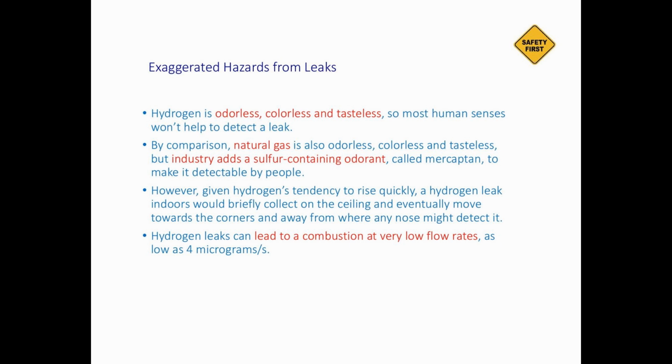By comparison, natural gas is also odorless, colorless, tasteless. As an industry practice, we always add some kind of sulfur-containing odorant, mercaptans. When you have leaks, you can smell it at home. But with hydrogen, we don't add anything, no sulfur components, no mercaptan. So you can't use your nose to smell it. Given hydrogen's tendency to rise quickly, hydrogen leaks indoors will collect on the ceiling because of the buoyancy effect. It could collect in corners or away from where any nose might detect it. Nose won't detect it anyway.